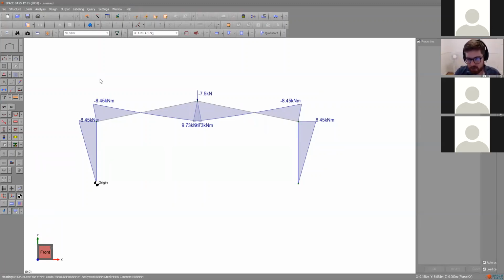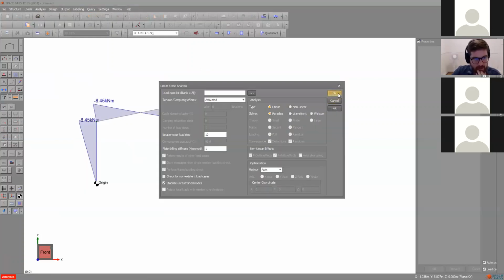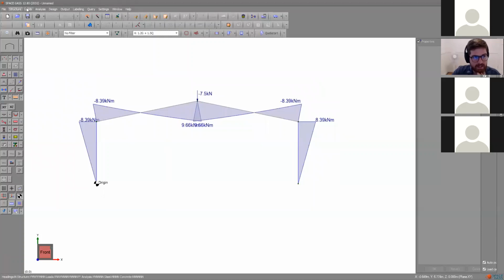For most of your course questions, I don't necessarily think you'll be asked to do much second order analysis. You're probably told about buckling and P-delta effects here and there. That's the computational analysis version of it. But in practice, often you'll be looking to run a second order or P-delta effect analysis just to check that the side sway in your system is insignificant, or the deflection isn't significant enough to really change the structural geometry and then the load carrying capability. I'm mostly going to keep talking about linear static analysis, but I just wanted to point out that that is there. And there's also things like buckling analyses and so on, which I won't go into.